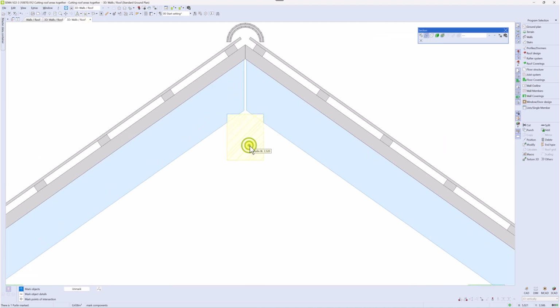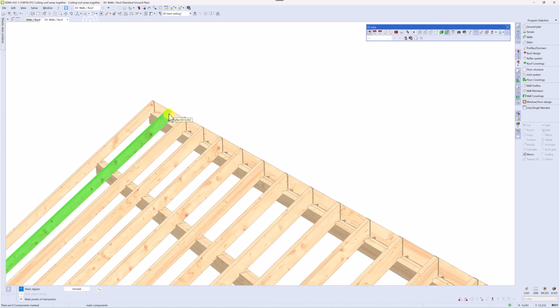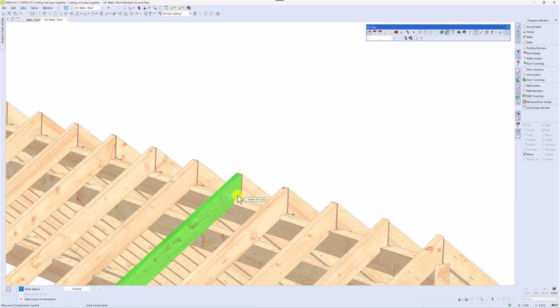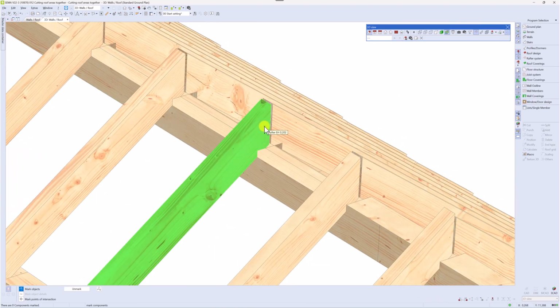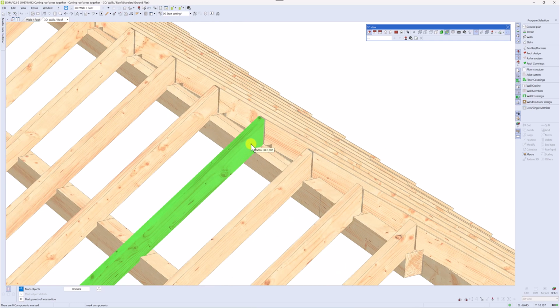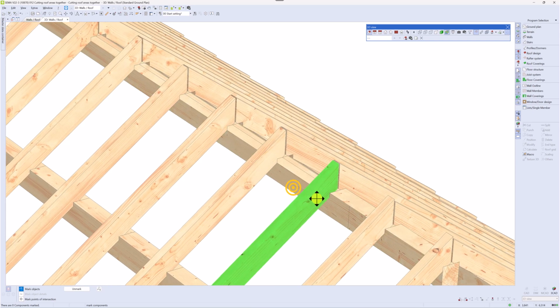and now we can mark the purlin, go to punch, and down here we can select the punching depth, and down here, probably you cannot see it, it's depth absolute, and with paste I can put it in. Now we can create a punch. Alright, now we can go back to 3D view, and we see the purlin has been cut, but still the rafters have the bird's mouth.